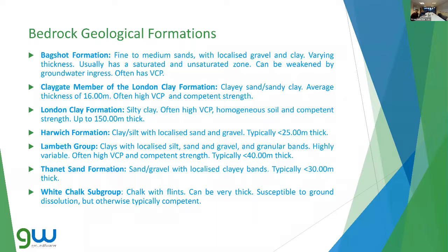Then you have the Thanet Formation, and outcropping at the edges of London you have the White Chalk Subgroup. So chalk lies beneath those formations. Central London is dominated by the London Clay, and we usually get a lot of projects that have to take into account the properties of London Clay. That's basically the main formation that you will find in central London.